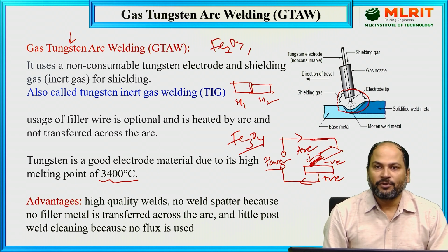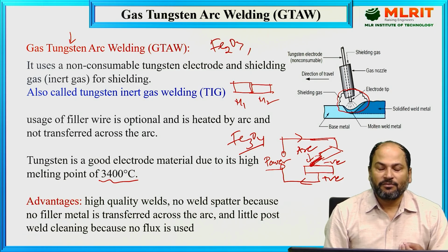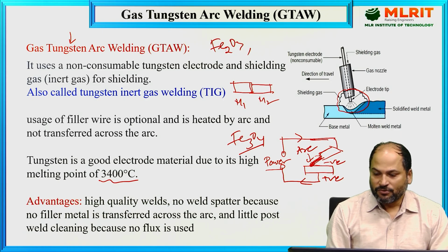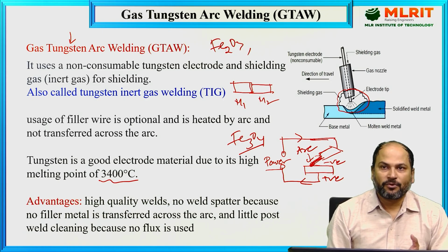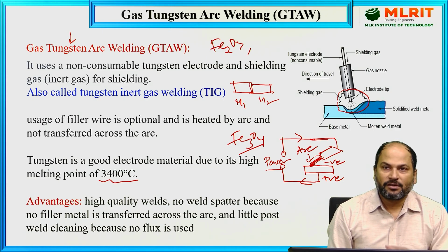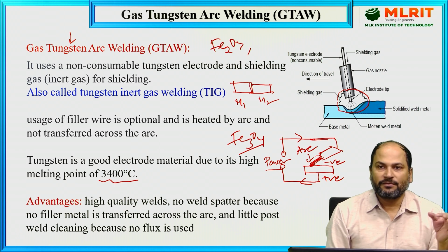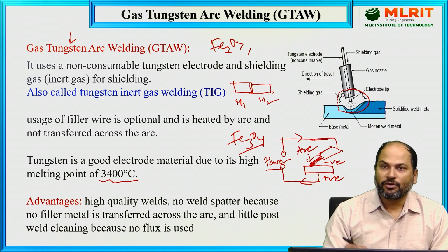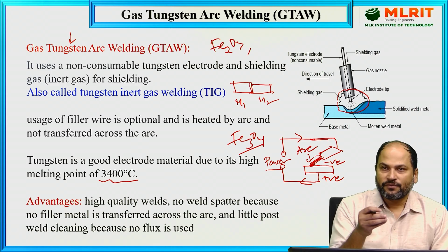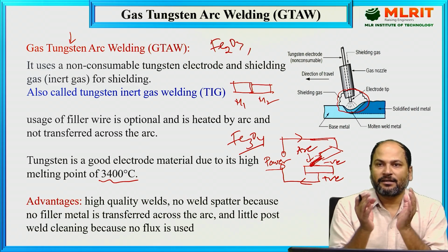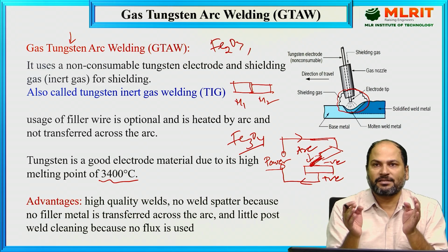Wherever we have to use this part in an application, even a slight vibration will create a lot of problems, and the chances are it will fracture, or there will be failure of the component. So we don't want this. How are we protecting our weld bed? There are two methods we have already discussed. Either we can use an electrode which is coated with flux, and as this electrode melts during the welding, the flux will act like a shield, simply covering the weld just like an umbrella.